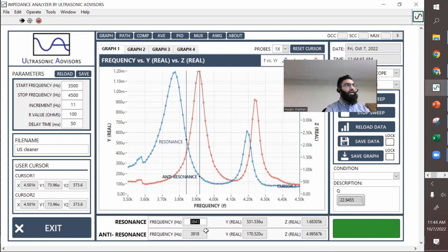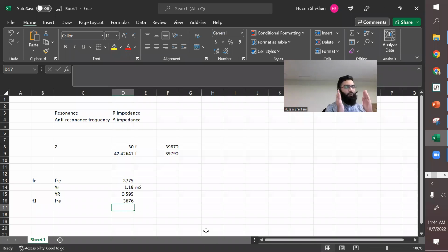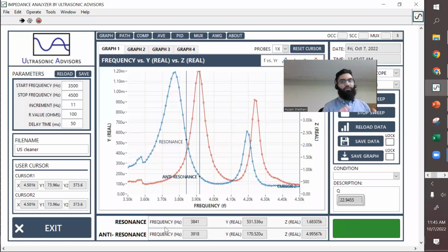This is the same theory, the same reason why the 3dB bandwidth works is the same reason why this works, except this works all the time, because the 3dB bandwidth can be misconstrued due to the capacitance. The real part of the admittance doesn't have that parallel capacitor messing up the phase and the absolute values. For example, if you have a mechanical system and you measure the absolute displacement versus frequency for a given force input, you can calculate the quality factor using the 3dB method.